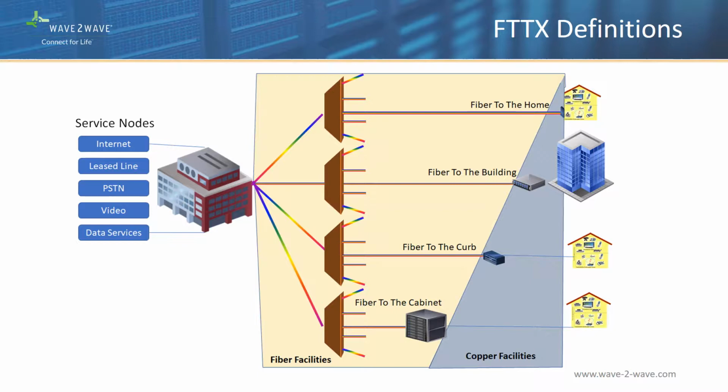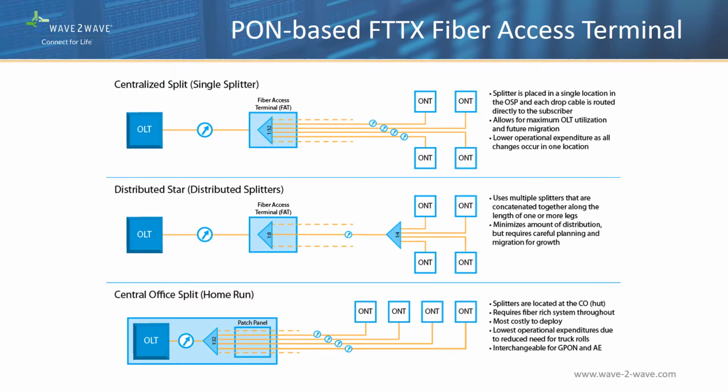Next slide, please. As the amount of fiber dramatically increases, the importance of properly managing fiber cables becomes a more crucial issue. Telcos use various approaches, including single splits, distributed splits, and centralized splits within the CO. The manner in which fiber cables are connected, terminated, routed, spliced, stored, and handled will directly and substantially impact the FTTX network's performance, stability, and more importantly, its profitability.